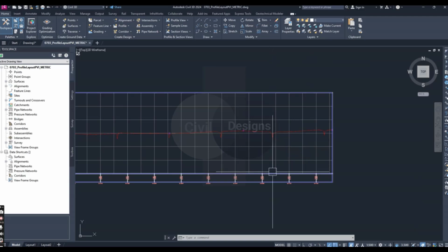The second method is entity based layout. It operates like horizontal alignment in terms of free, floating and fixed entities. The PVI points are derived from pass-through points and other parameters that are used to create the entities. Entity-based editing allows for the selection of individual entities and editing in an individual component dialog. We will work with both methods in the next exercises to illustrate a variety of creation and editing techniques.